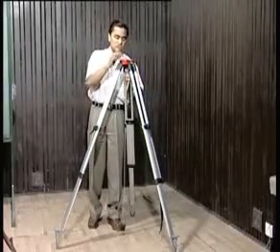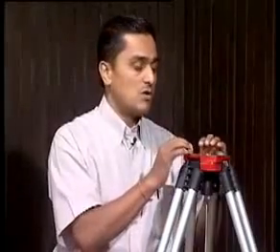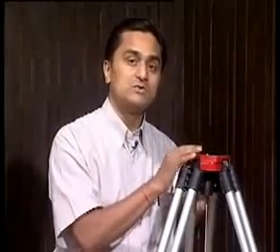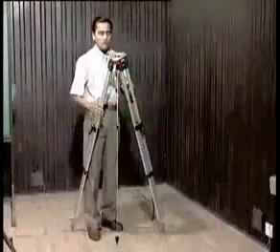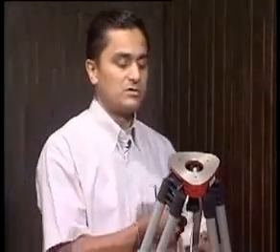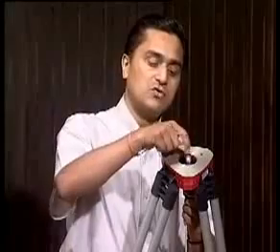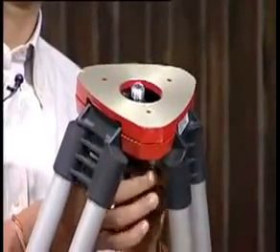And it is also approximately centered over that point. Now at that stage we'll bring our theodolite and put it on top of this. One more thing in the tripod head which is important: if I show you like this, we have an assembly which can move. Once I bring my theodolite, I can put it in such a way that it goes into this bolt. So this is the bolt for the theodolite. Now I can bolt it into the theodolite bottom.